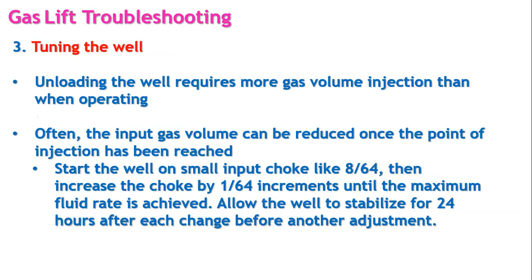Tuning the well is once we have the continuous, stable production. We have to consider that to unload the well, we require more gas volume injection than when we are in operation. That's one of the drawbacks of the system, that to unload the well, we need a lot of gas volume, but during the operations, the volume is considerably lower than that initially.